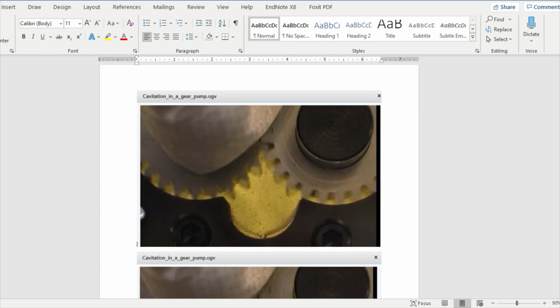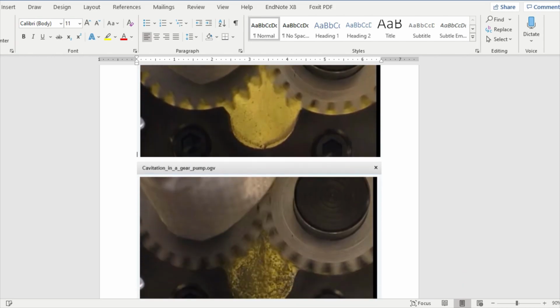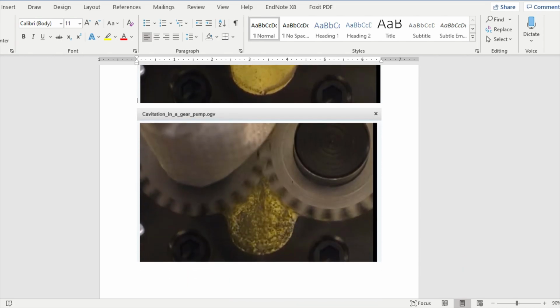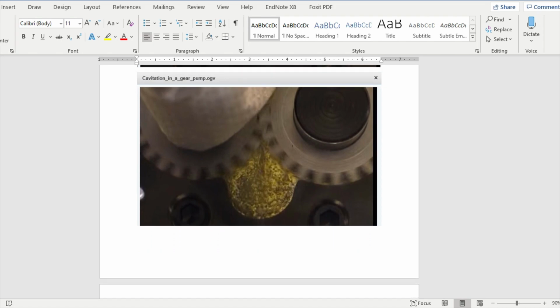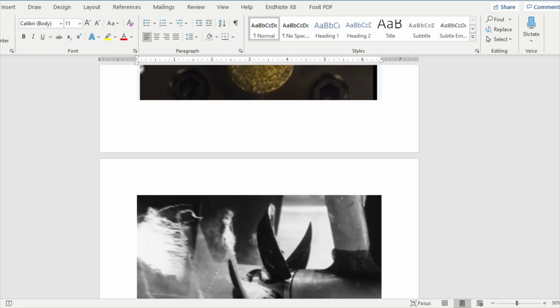This is a lubricating oil. So as they spin, you have high relative velocity between the fluid, which is mostly stationary down here, and the actual gear teeth. And as they spin up, it can cause bubbles to form because of the pressure differences. It's almost kind of like creating a vacuum, so a bubble will form. And then if the bubbles form, when they pop on the surface, it actually causes a large pressure gradient.